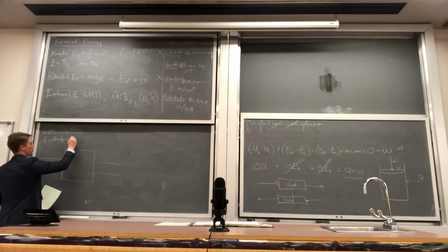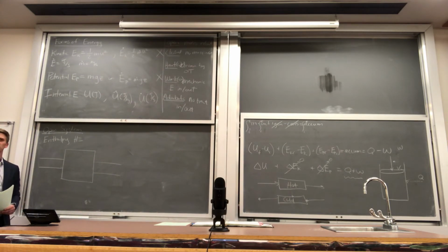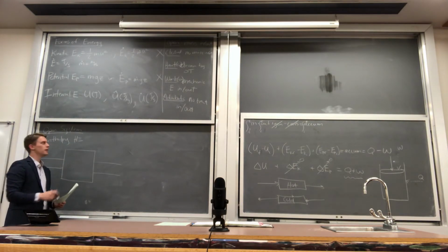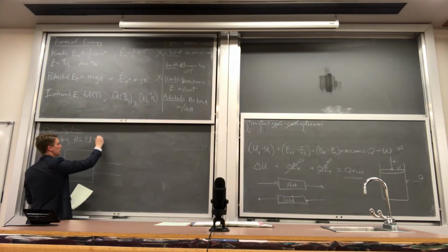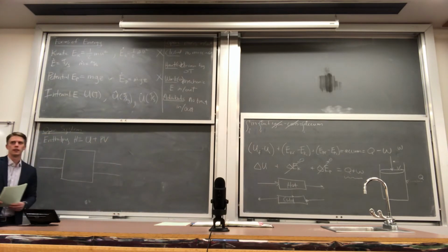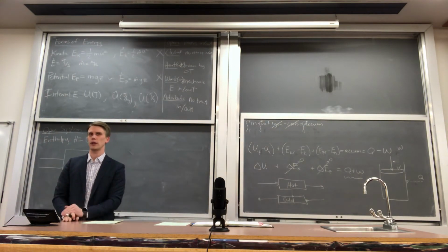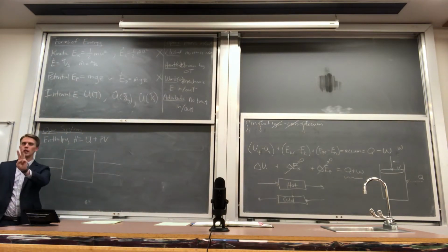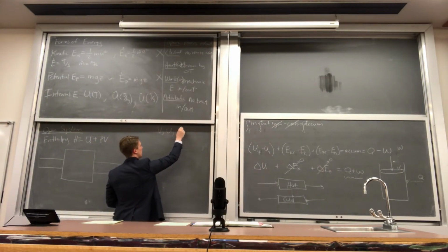So what is the definition of enthalpy? It should be a well-structured equation. It's U plus PV. The key thing to remember about thermodynamics, and this is something I stress very heavily in the graduate thermodynamics class I teach to MS and PhD students, is that there are 3 fundamental variables to the universe: V, U, and S.